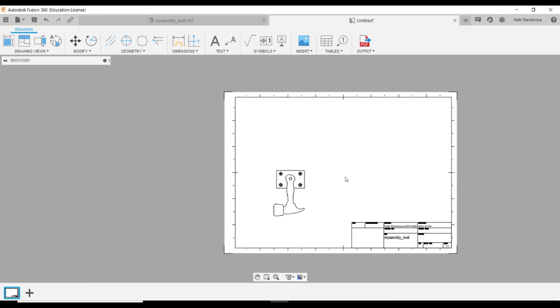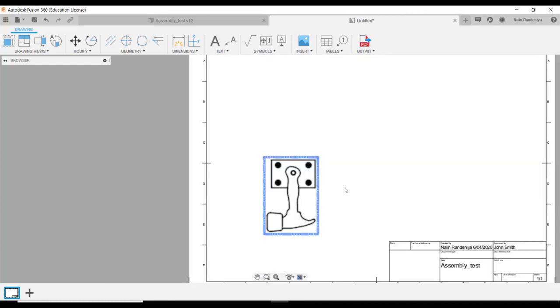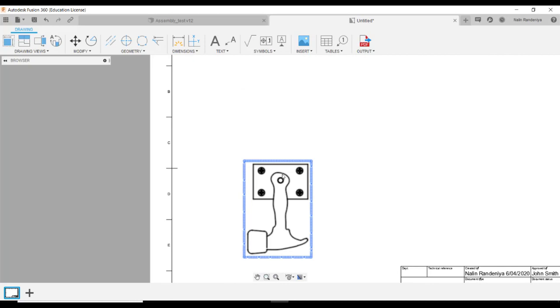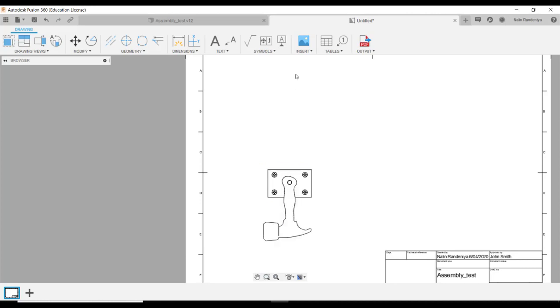Since these drawings go in black and white, and we need the ultimate clarity, we try to reduce unnecessary lines as much as we can. If it's necessary to show some dimensions or some other details, then we definitely include them. Then we want the projections. Then we have projected views. Click on that button, then click on the view that you want the projections of.